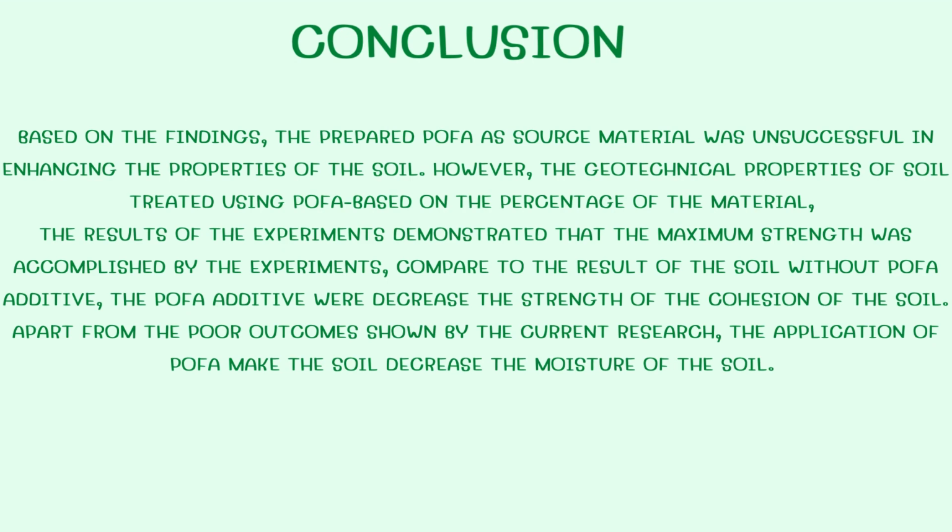So for the conclusion, based on the findings, the prepared POFA as a source material was unsuccessful in enhancing the properties of soil. However, the geotechnical properties of soil treated using POFA depend on the percentage of the material.